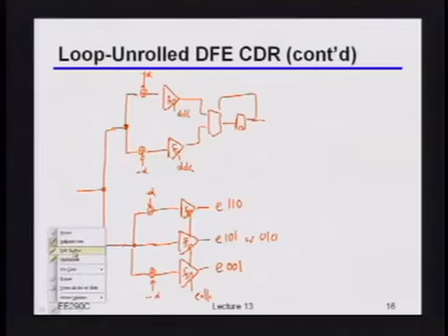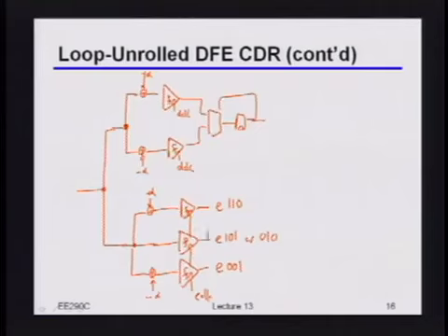Now, by the way, I should mention, this is kind of like building a fractionally spaced equalizer, right? In the sense that you're canceling the ISI on the edge position, right? But it's another way of looking at things in the sense that you're really only doing it for this one unrolled tap, right? And you're trying to do it in a way that you're clever about when it is that you use which estimate, okay?